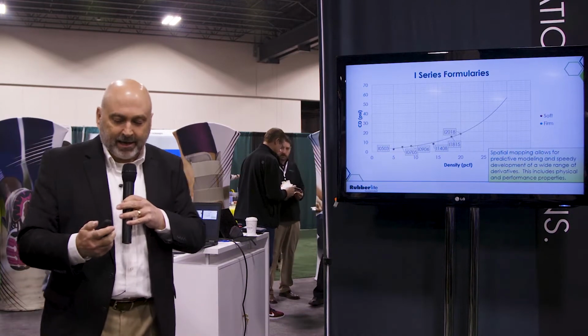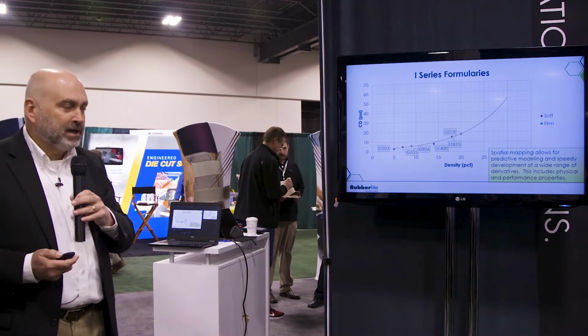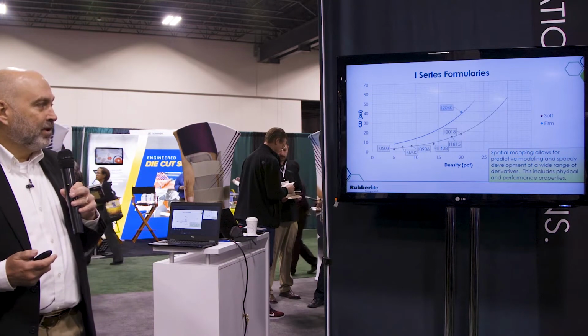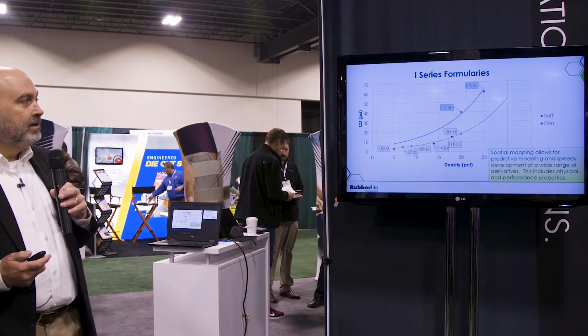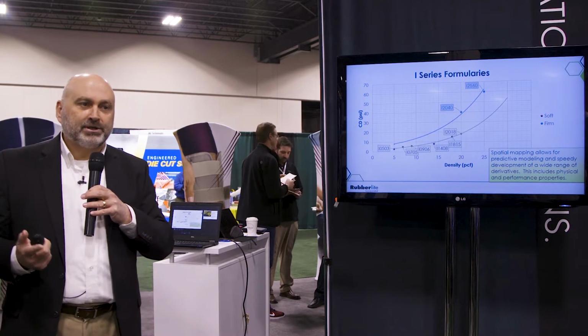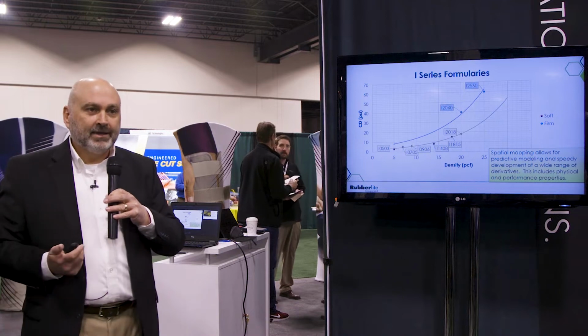Now I take that same chemistry, move the molecules around a little bit, change the process conditions, and now we have a very firm product. Now you see I can make a material that's as hard as 60 psi compression deflection at a nominal density of about 25.